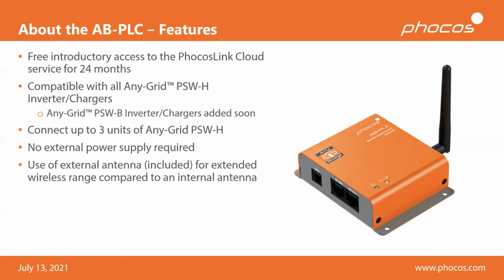And furthermore, if that's not sufficient, you can go ahead and exchange that external antenna for a different model. You can get higher gain antennas, or even more specifically, you can get directional antennas. These types of stick antennas are called omnidirectional, so they will radiate in all directions, which essentially means that you have access from all directions. That's the upside. The downside is you have lower range than a directional antenna.